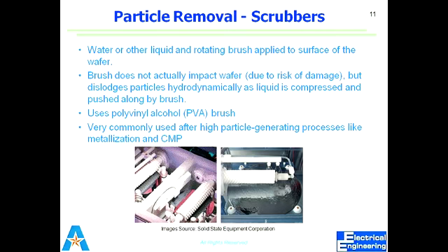If you remember the slides last time, there was a CMP step, the chemical mechanical polishing, when we deposit oxide in the trenches, and after that we do chemical mechanical planarization, so we remove that oxide layer. Remember, that is shallow trench isolation. In this shallow trench isolation, we talked about CMP.